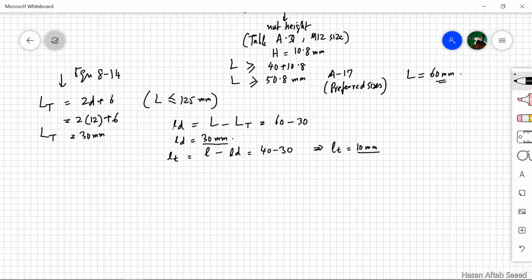Now, if we are going to find out the stiffnesses KB and KC, and then C, we also need the areas of the threaded part as well as the unthreaded part. So let's take those up now. The area of the unthreaded part, or the shank part, is very simple, π/4 d squared. This is the nominal diameter, and just using the cross-section area of a cylinder, that comes out to be 113.1 square millimeter. AT is even simpler.